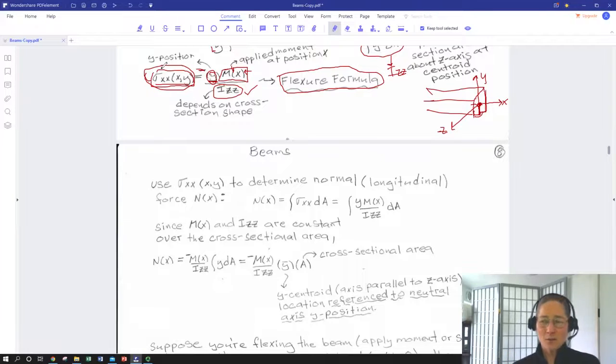So if you really want to apply a lot of tensile stress to something, just support it between 2 points and step on it in the middle. It's much easier to get a huge tensile stress down on that bottom curved surface than it is to actually grab something and yank on it. So we'll have an example later on where we'll take a look at relative magnitudes. In real practice, you should consider both. But the flexure formula takes into account what is typically the largest one.